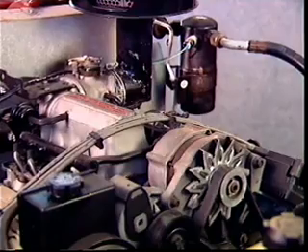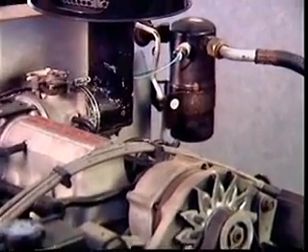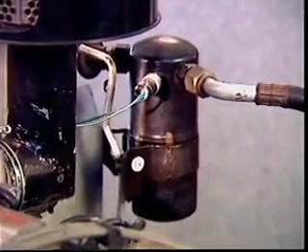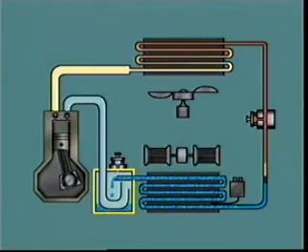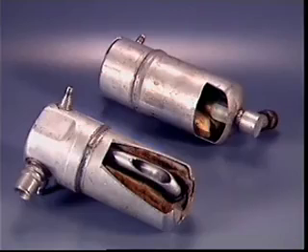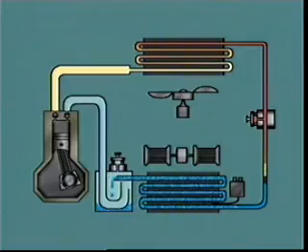The refrigerant in the evaporator flows onto the accumulator. The accumulator acts as a storage volume for the refrigerant and also separates liquid from vapor. Refrigerant vapor enters at the top of the accumulator. Any liquid refrigerant falls to the bottom. The accumulator is made from aluminium and has a large surface area. This assists the final evaporation of any liquid refrigerant leaving the evaporator.